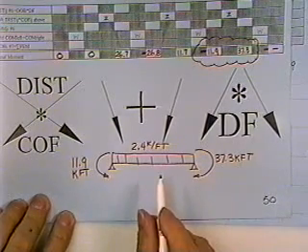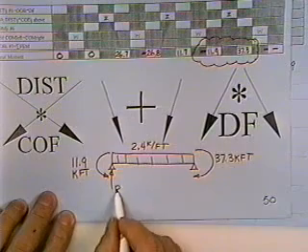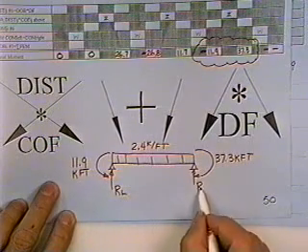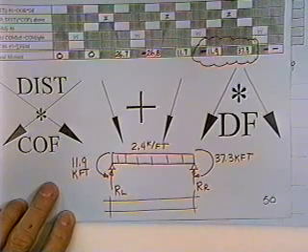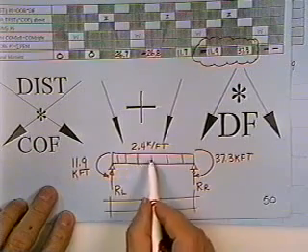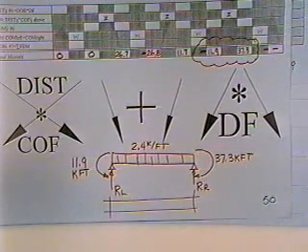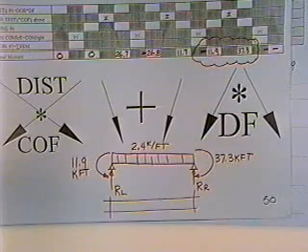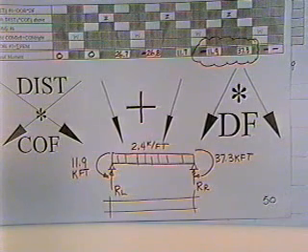You draw a shear moment diagram for this dude just like you did for everybody else. You use statics to solve for the reaction on the left and the reaction on the right. You come down and draw shear and bending moments for that beam, and you have the maximum shears and moments to be designed for. Now, I guess it's why they give you all day to take the quiz, because you see this could get to be a time-consuming process. But there are definitely some problems on there, almost invariably, that require you to get the moments. And I know they could care less how you get the moments, but it's got to be done somehow.